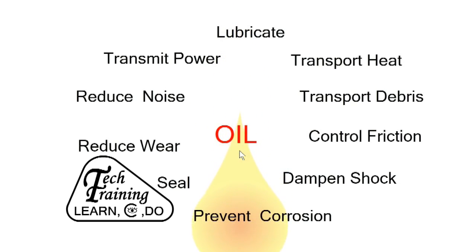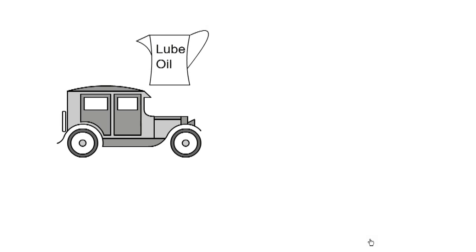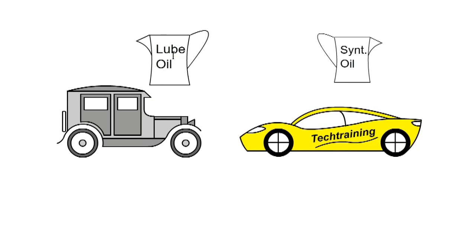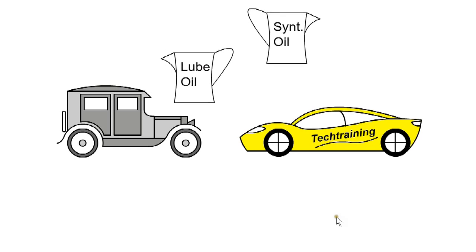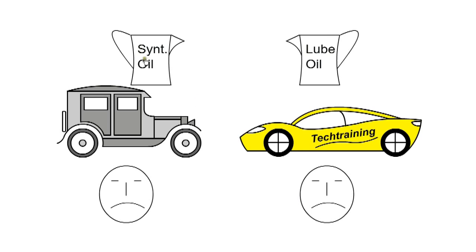Modern engines use low viscosity synthetic oil as the clearances in the bearing have been reduced and less energy is required to pump. The oil must fulfill other tasks, such as hydraulic oil for the cam timing advance system and hydraulic tappets. The grade and viscosity must be suitable for the engine design and operating conditions. Because a vintage car has 300,000 miles and has used a certain type of oil, it does not mean that the same oil will be suitable for a modern high-efficiency engine. Likewise, an expensive, fully synthetic, low-viscosity oil will not be suitable for a vintage car.